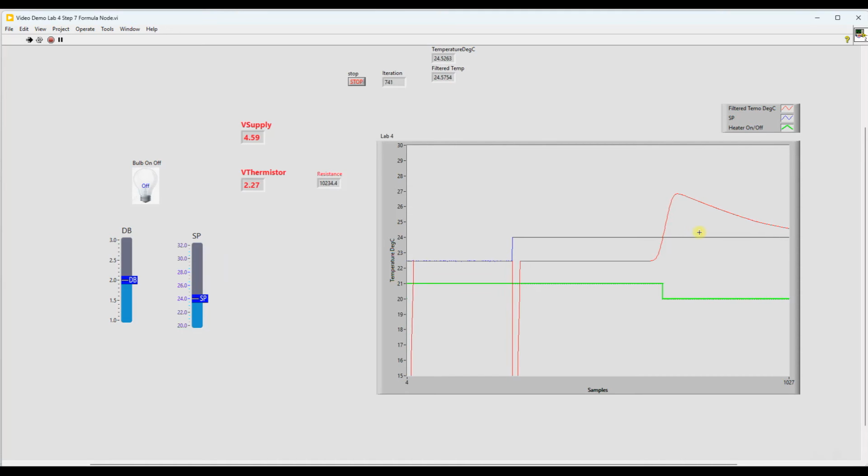Okay, and in time that temperature will drop down. And like I said, I'm not using the deadband right now, but your program must use a deadband. Okay, and when I heat it up a little bit, okay, so this program has no hysteresis, no deadband. It switches right on that set point, but that's not a good type of control, so we want to add some deadband. But everything seems to be working okay.